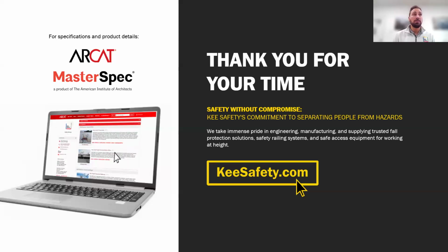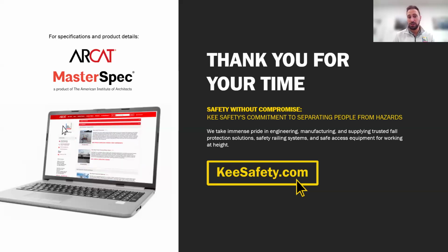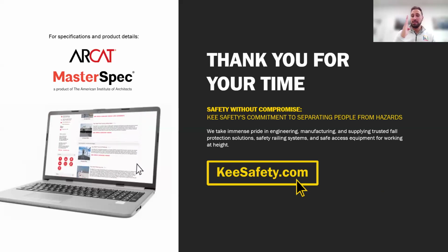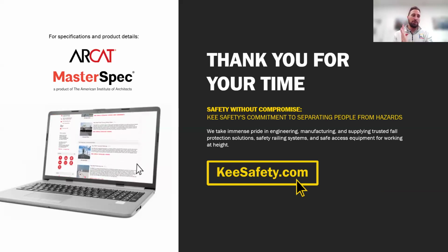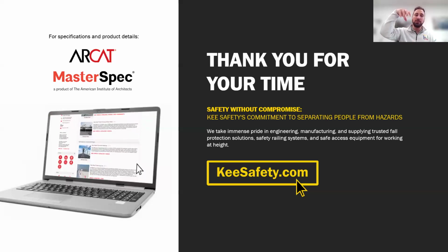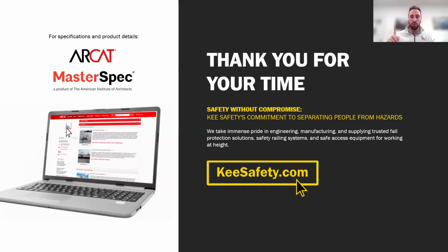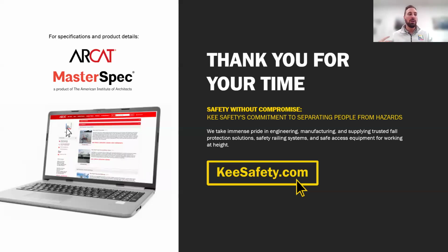No, because we don't know what's going on inside of the 15 feet, right? So that warning line is to protect people from going within that, we call it the danger zone, within 15 feet of the roof edge. If I'm doing work that is not temporary and not infrequent within that 15-foot zone, the warning line is required. The anchor points would be what you would use if you were to go outside of that zone.